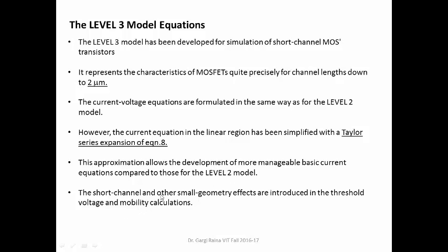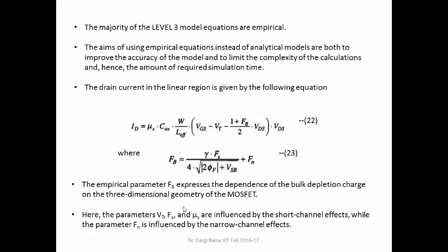The short channel and other small geometry effects are introduced in the threshold voltage and the mobility calculation. The majority of the level 3 model equations are empirical. The aim of using empirical equations instead of analytical models is to increase the accuracy of the model and to limit the complexity of the calculations. Therefore, you are also reducing the simulation time.